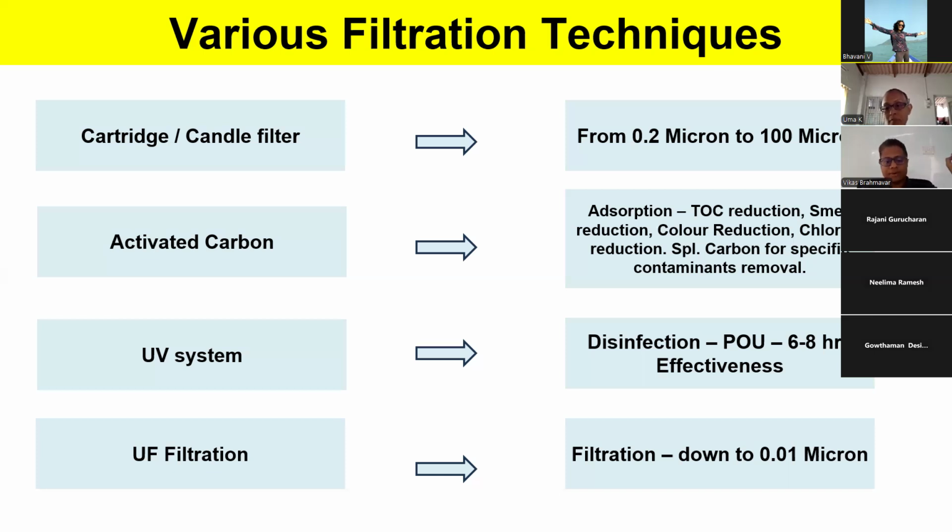you should be sure that the water has no other contaminants, just a basic cartridge filter. Activated carbon filter, there are different grades of carbon based on the iodine value of the carbon. So they grade it based on the iodine value of the carbon which you buy, right? The higher the iodine value, the better for absorption. More contaminants get absorbed.